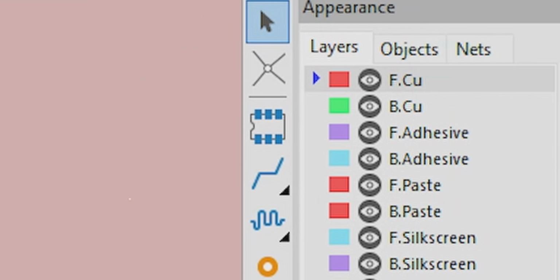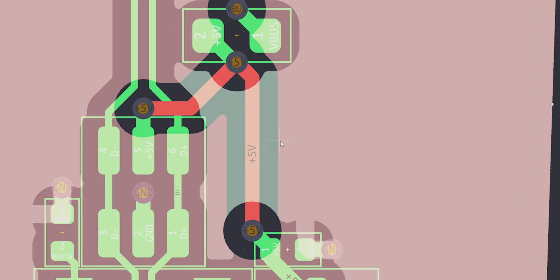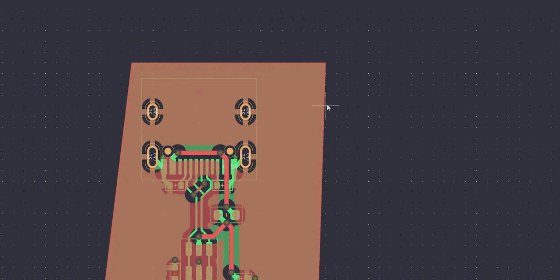And one thing that's actually pretty typical with PCBs when you're getting a little bit more advanced like this is to use what's known as a 4-layer board, where in the middle there'd be 2 additional layers. They'd actually be completely solid, like filled copper zones. And that would help with things like EMI interference, which is, if I come up here, let me just delete this filled zone really quick.